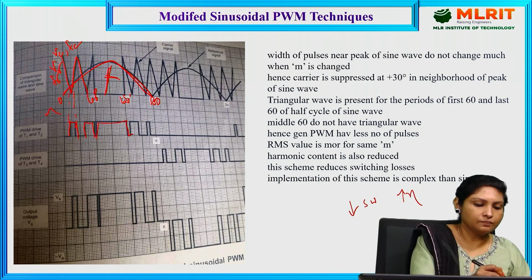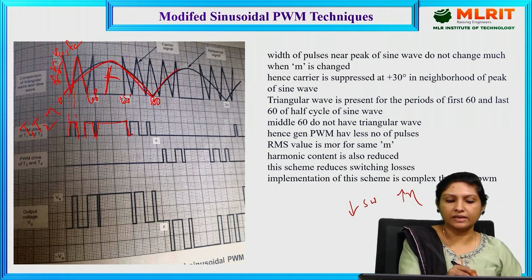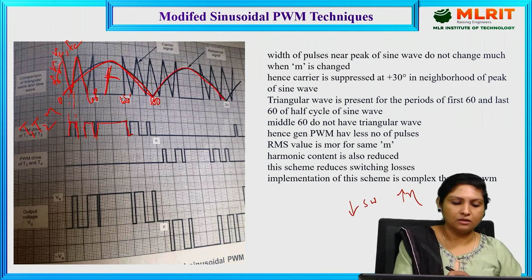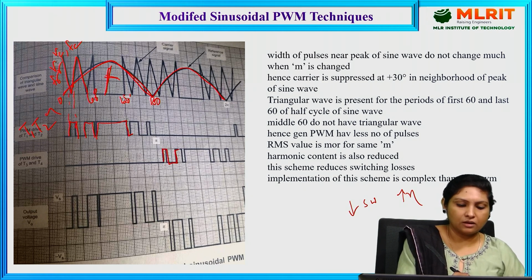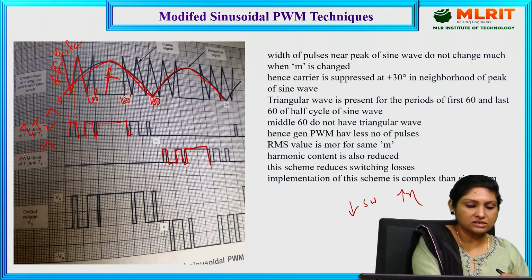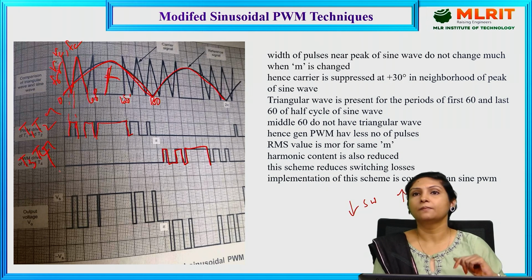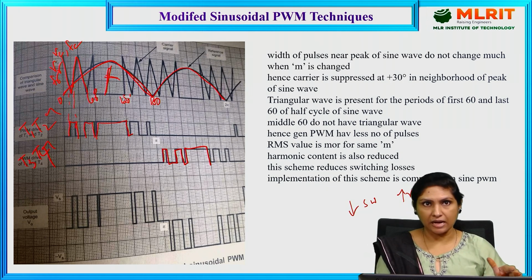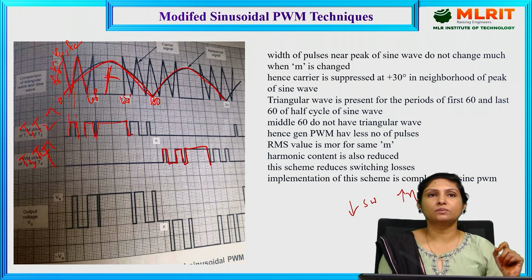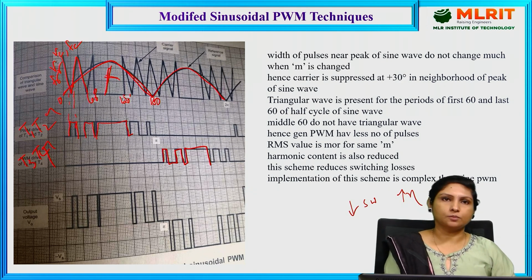And this is the comparison of another, second sinusoidal waveform with the carrier, resulting in the pulses which are actually required for transistors 3 and 4. This will now act as a base drive for transistors 3 and 4, such that these will be triggering the transistors respectively, which gives the resultant controlled pulse width modulated inverter output.